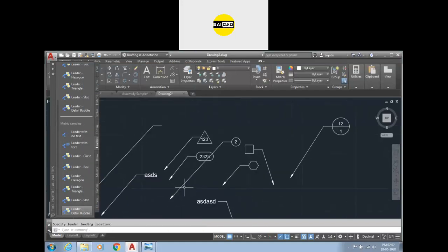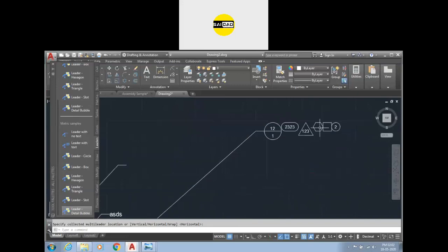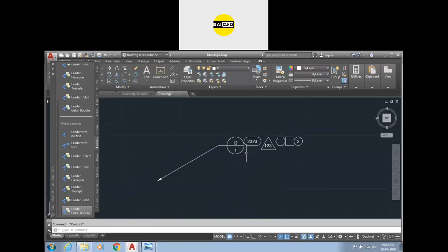Like that. To combine the properties of all these leaders into one, we have the option here called collect. Select all the leaders, press enter, and now you can see all the leaders will be combined like that. So you can just attach the arrow anywhere and the leader can be created like that. Is it okay? Any question on leaders on the tool palette?